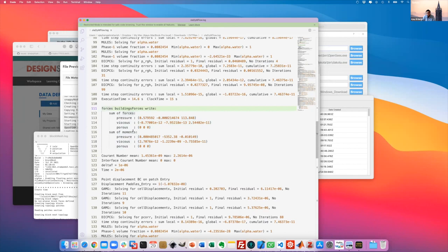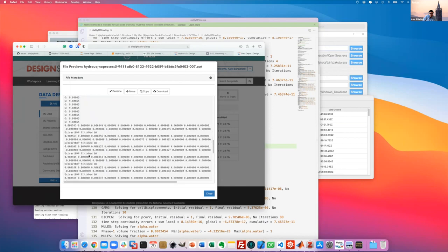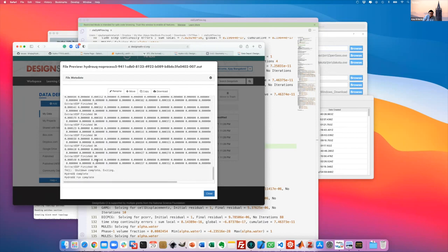So for example, if you don't have any building forces at all, like the event did not run, the OpenFOAM simulation did not run, then it is going to give you an error because there's nothing to write there. Unless the OpenFOAM simulation happened, there's nothing to write. And then it's going to start your Dakota, where you can see that all the Dakota was being run here, right?